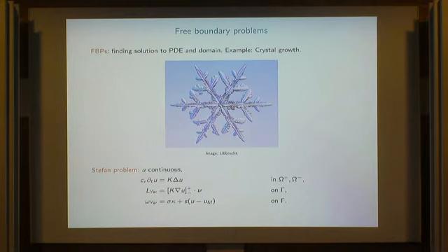V nu is the normal velocity of the interface between the solid and the liquid. This latent heat then is transported away. This is the net flux of the energy into this free boundary, the corresponding heat flux. These two equations describe the energy balance of the system.